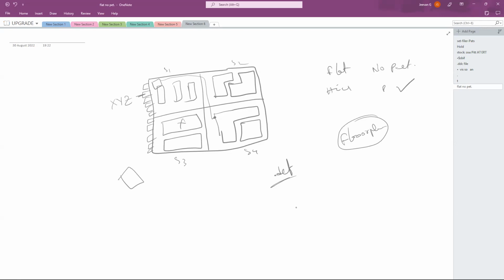So you can see in your particular block where your macros are. For the floor plan you don't have cells, right? If you have placed any cells in the floor plan itself, you can see what those are and where they got placed. These are like some kind of ECOs, or because of some of the pre-routes, all these things.